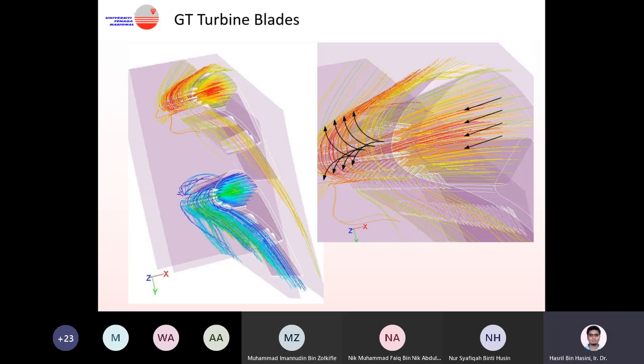When it comes out from the front here, and the hot exhaust gas is coming from the front, the air is going back through the leading edge, and then this air automatically forms a layer on the blade to protect it, basically. So that is one of the technologies they use in terms of the cooling air for the nozzle, and cooling air for the blade as well.